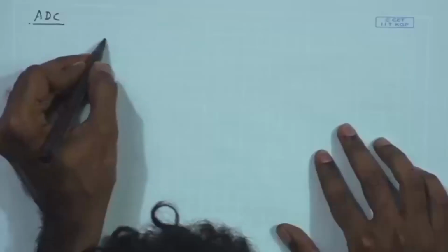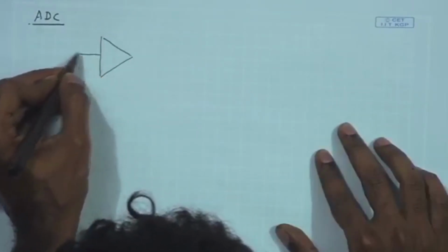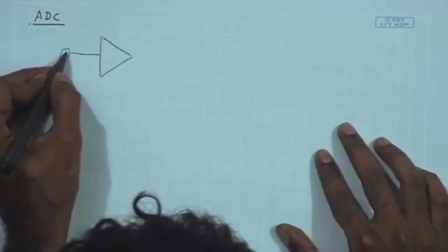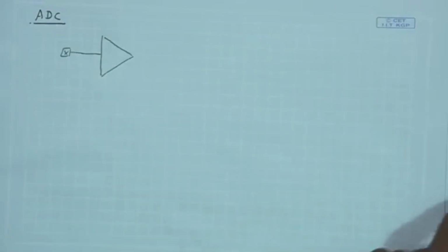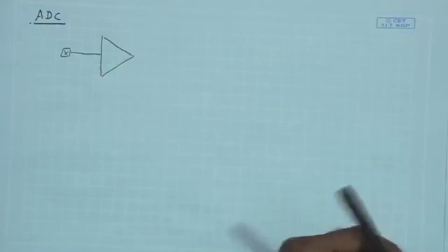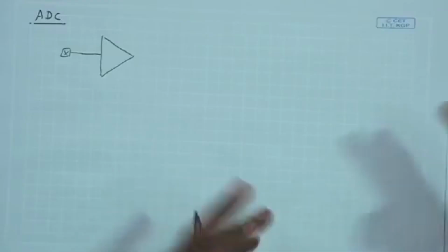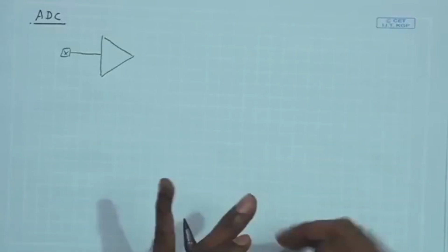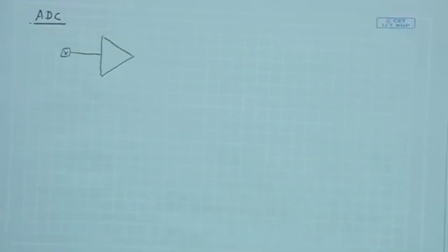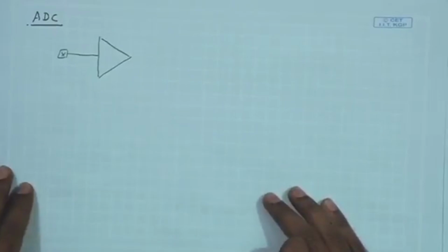We have the front end amplifier, for which we have already had detailed discussion, which is acquiring the data from the sensor, and we have seen the design issues associated with the front end amplifier, starting from high level specification, going down to the blocks and the circuit level specification, transistor level design, sizing, addressing different issues starting from noise, bandwidth, gain, linearity, precision, and so on.